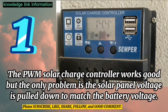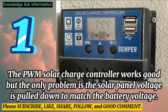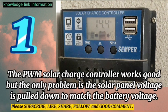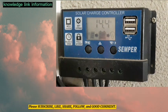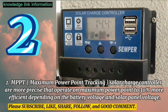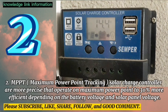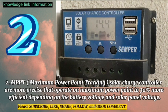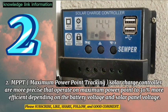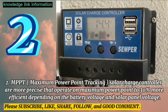The PWM solar charge controller works well, but the only problem is the solar panel voltage is pulled down to match the battery voltage. Number 2. MPPT, maximum power point tracking. This solar charge controller is more precise, operating only at the maximum power point, up to 30% more efficient depending on the battery voltage and solar panel voltage.